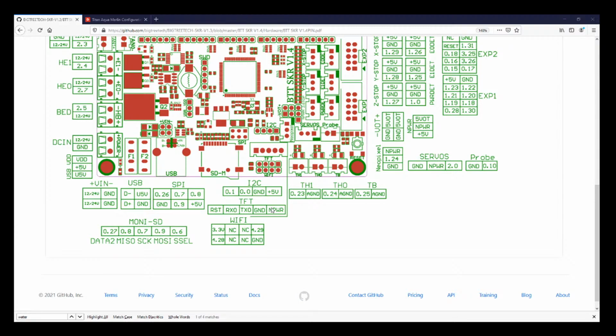So the next thing we can do is this. This will help us, hopefully. We're going to connect this up and see if we get voltage. So I'm going to connect it right here. And then I'm going to look on here and see if I can find voltage. And we'll probably have to look around the board a little. So it says that 5 volts is on the right side. And the right side goes to, I believe, this one, which is TX. So it might be a cabling issue. But let's cheat and see what the multimeter says.